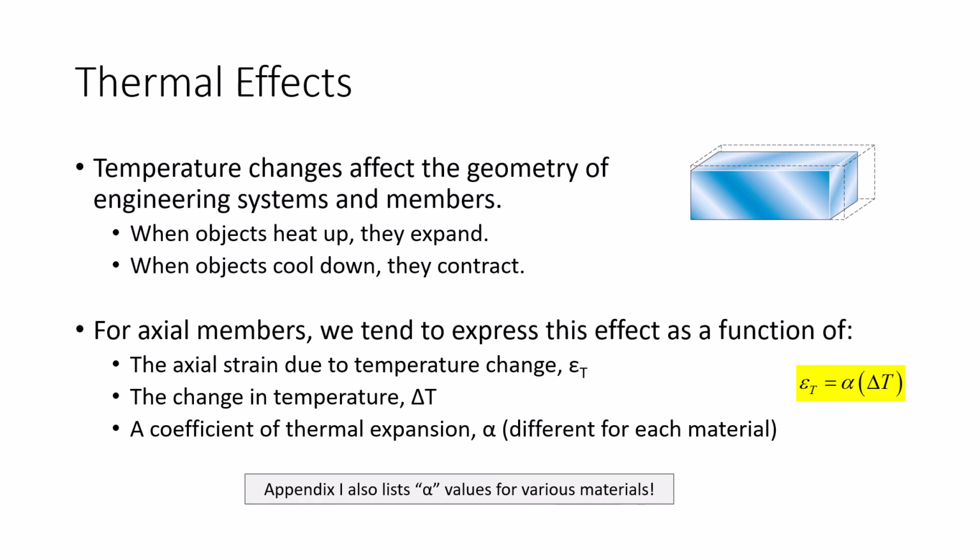So if you have a bridge out in West Virginia that's experiencing single-digit temperatures today, that's experiencing triple-digit temperatures in the summer, it's obviously going to expand and contract, but the steel is not going to expand at a significantly different rate than the concrete is. So you don't have the rebar getting longer at a different rate than the concrete, because if it is, you have rebar inside the beam that would be causing cracking because it's expanding or contracting at a different rate than the concrete is, and that actually doesn't happen. The alpha values for steel and concrete are serendipitously very, very similar.